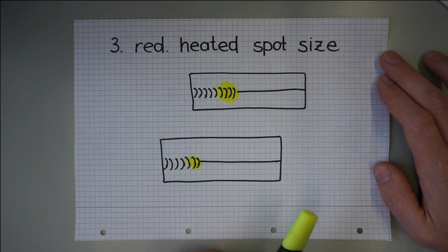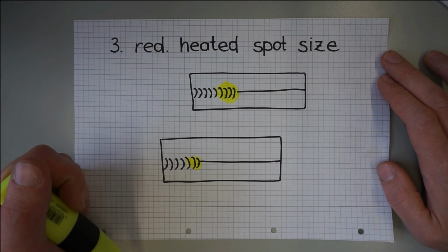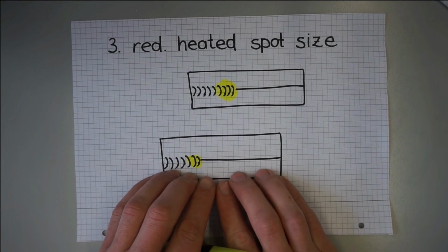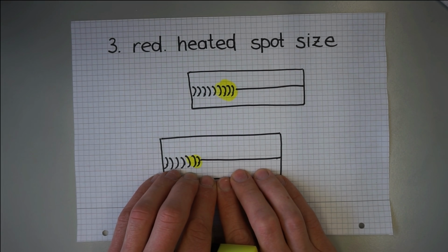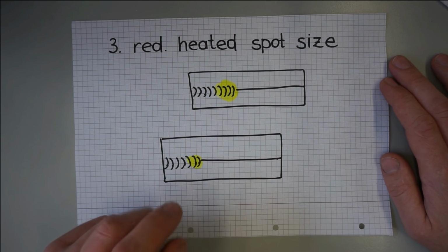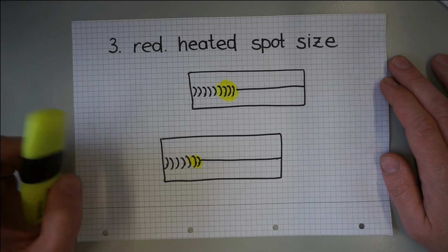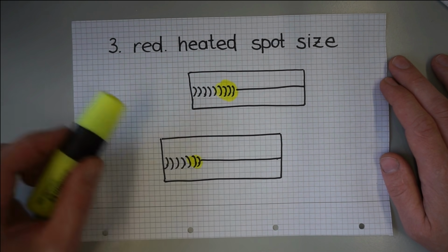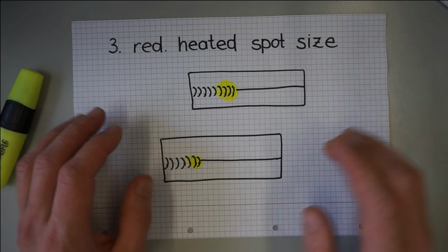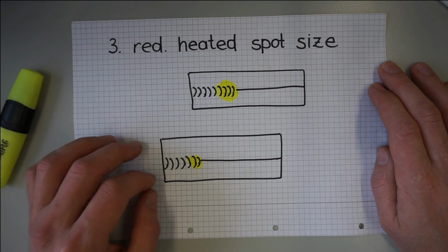Well, and the last method of reducing heated spot size is using heat sinks, typically out of copper or aluminum, placed close to the weld. Even though this might require more welding current, the heated spot size may become smaller since most of the welding heat is conducted into the heatsink. But here we must make sure at the same time not to increase workpiece rigidity with the heatsink, otherwise strategy number 2 is injured.